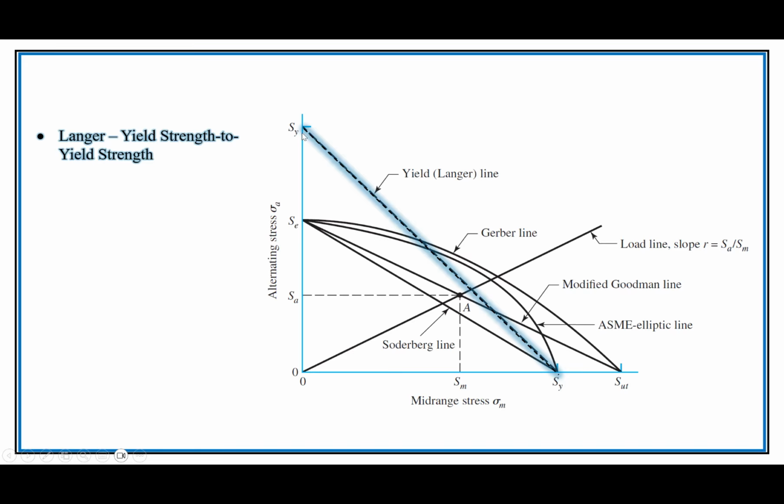As I said, we attach the yield strength to yield strength, and I think of this when we go to the Goodman, and we call it the modified Goodman, as being the thing that we're doing to modify it. Anything over to this side, we're really saying it's going to yield, but then we start to talk about the fatigue. But maybe if it yields, it's already failed, right?